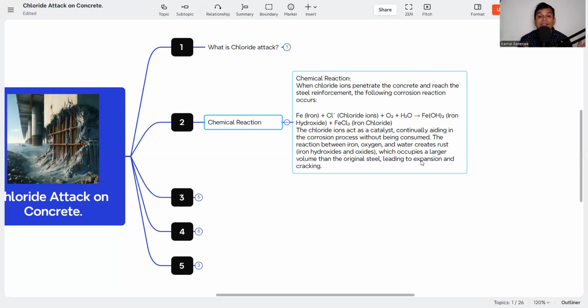One, this chemical reaction with the reinforcement, and reinforcement corrosion is happening. The backbone or the main skeleton, that reinforcement, becomes damaged. So durability is a problem. And in another way, concrete cracking is happening, concrete spalling. The concrete itself is also deteriorating. So in this chloride attack, both the steel and the concrete are equally damaged.